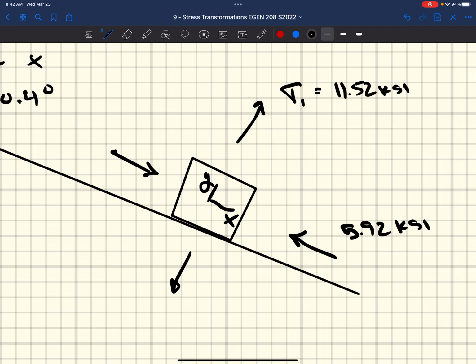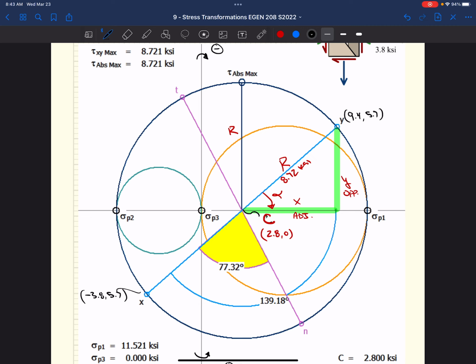Well, when you depict that known stress state in that chalk, and we put it into pure shear, right? It has zero normal stress. It just has shear stress, right? The two points we're going to plot are going to be along this y-axis. So what does that mean? Well, if we rotate Mohr's circle and figure out our principal stresses, that's going to be 90 degrees. Well, in the real world, that's 45.